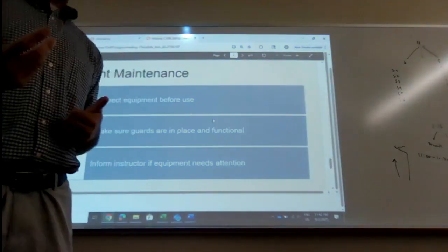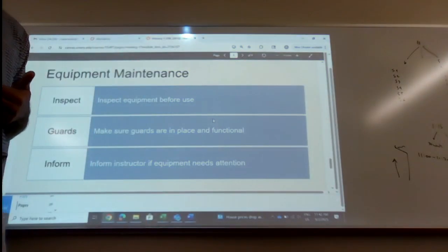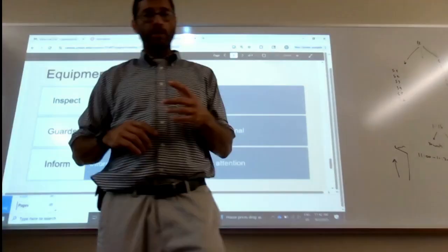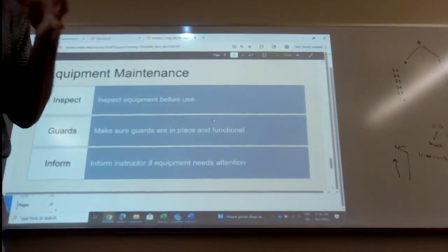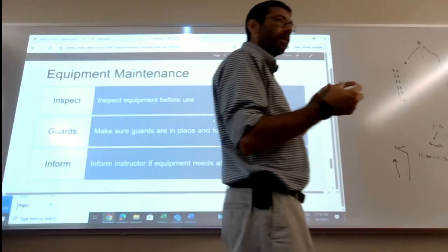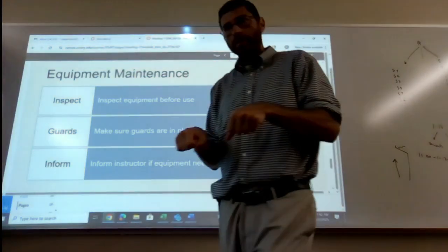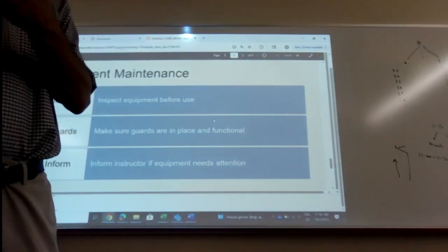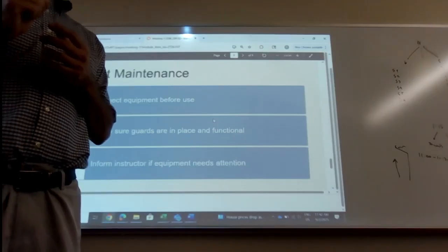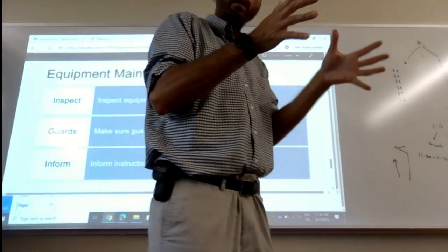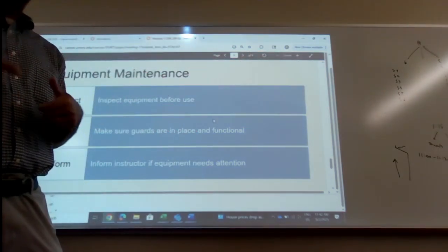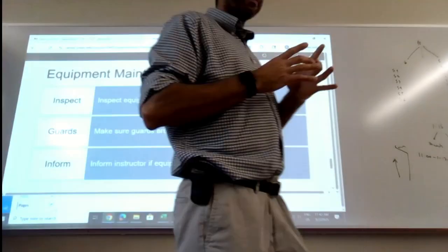But what does that mean? It's a school. Sometimes, one common thing to happen is the grinding wheel. The grinding wheel is a lot of sand that's bound with a resin, right? If somebody is pushing a cart and hits the grinding wheel on the side, and cracks the grinding wheel, and then the wheel is sitting there, looks good. Once you turn it on, now you have the rotation. Now there is a force pushing out.